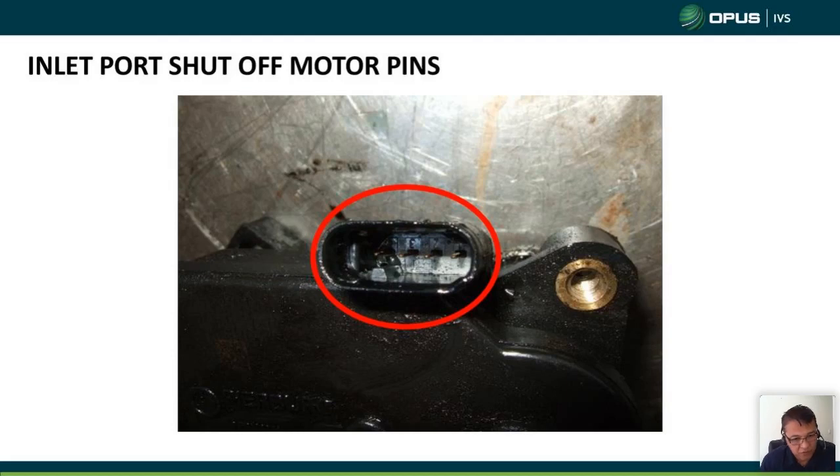Bear in mind with those fault codes as well, because if the fault code shows many components short circuit to ground, for sure there will be a blown fuse. Off the top of my head, it's in the fuse box on the right side of the engine bay, fuse 105, I think 103, mostly a 15 amp fuse.